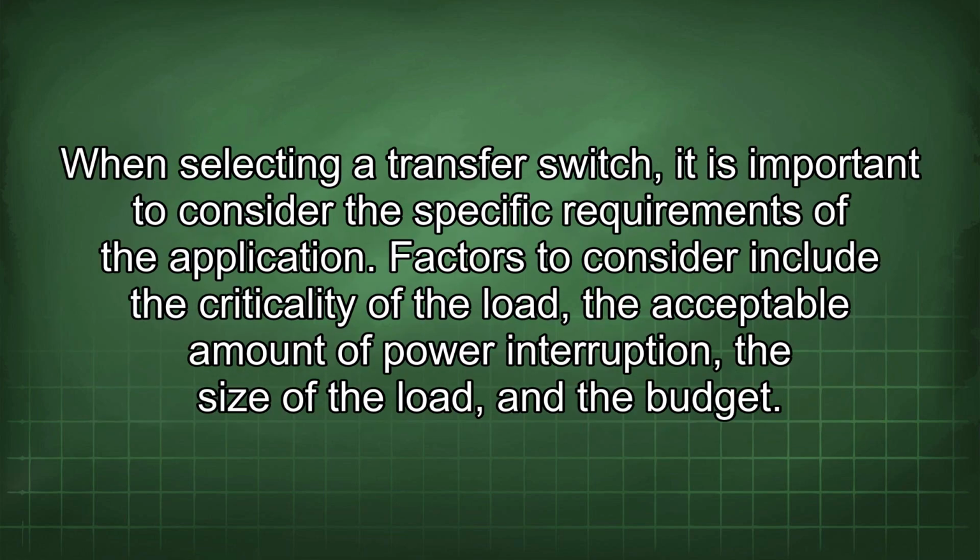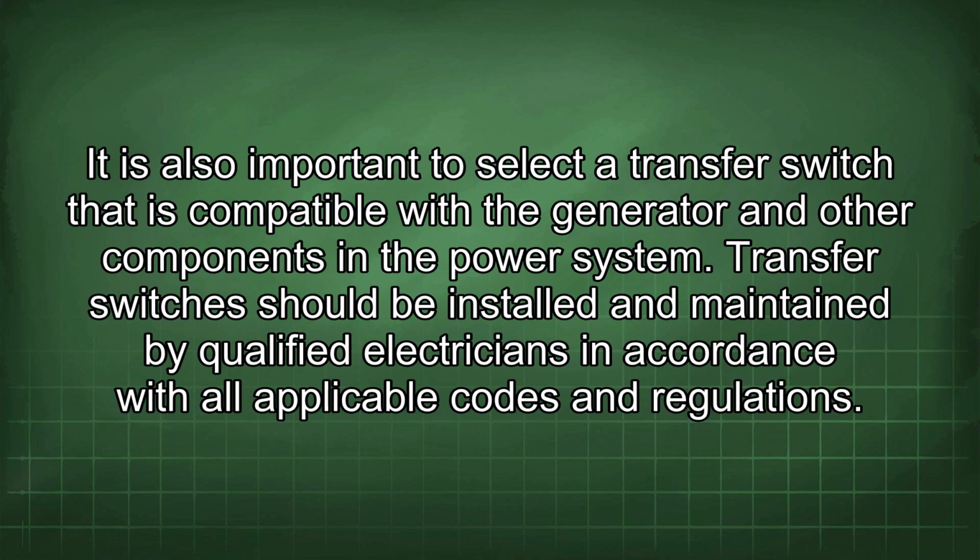When selecting a transfer switch, it is important to consider the specific requirements of the application. Factors to consider include the criticality of the load, the acceptable amount of power interruption, the size of the load, and the budget. It is also important to select a transfer switch that is compatible with the generator and other components in the power system.